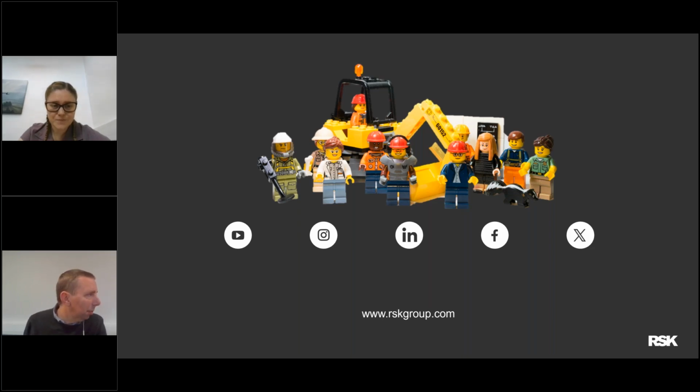Okay, we've had a few people ask, how do we determine the number and type of boreholes or investigation locations to undertake, particularly the depth of investigation? So for the number of locations, I can't remember exactly which guidance document it is in, but there is a guidance document from that list that I put together that will give you an example of what grids you should use for your investigation.